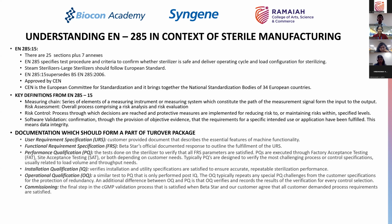So the URS and the DQ are what you will try and check during factory acceptance test, and you can't of course check everything there because you can't carry your garment loads, you can't carry your actual loads there, right? So you agree to what tests you can do at the factory, and then based on that give the clearance for the vendor to be able to ship it.